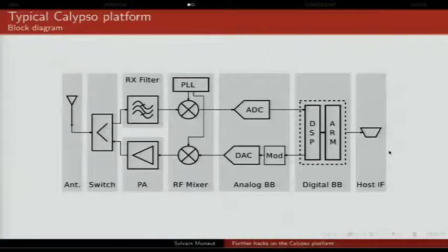So now that we know a little bit about GSM and how a network acts, we need to know exactly how a phone works, or more specifically, this phone, since it's our target today. So if you just look here, it all starts with the antenna. It's a standard antenna, nothing special about it. It's directly connected to the transmit and receive switch. As I said, the phone can't transmit and receive at the same time, so they just use a switch.